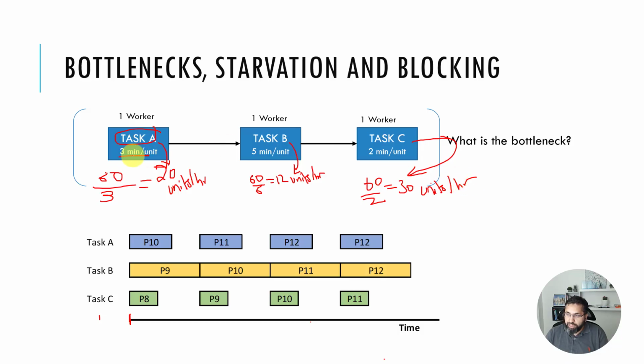And this is very standard. You take the cycle time, you do 1 over the cycle time. If you want to do capacity per hour, you'll multiply it by 60 minutes per hour, because cycle time is in minutes. You have to convert from minutes to hours. Or if you want to do it by day, there are 8 hours in a day, 60 minutes in an hour, 480 minutes in a day. 480 divided by the cycle time will give you the capacity per day, right?